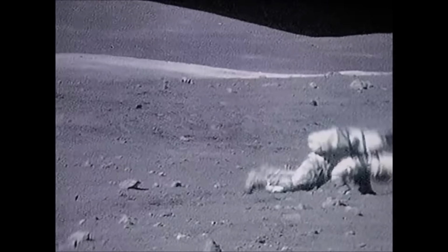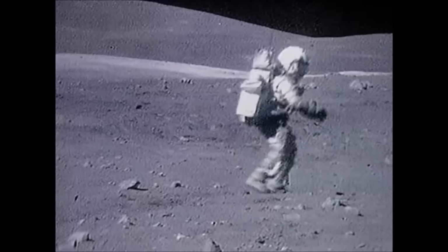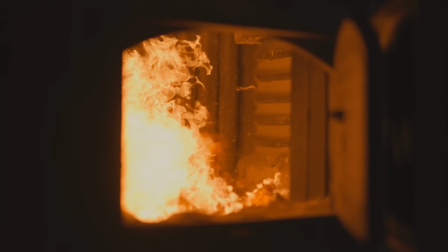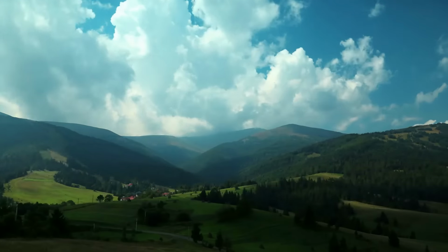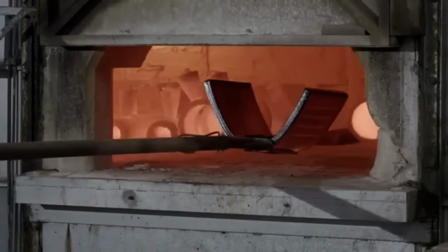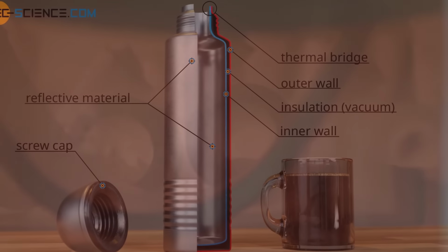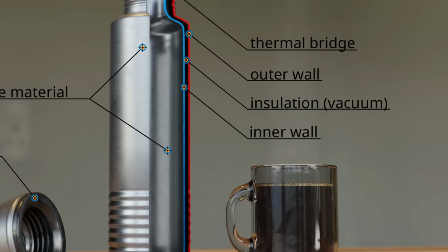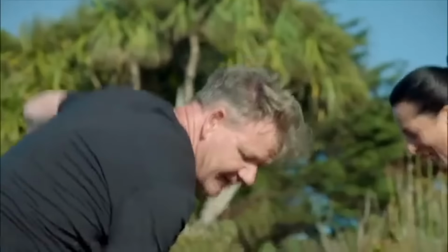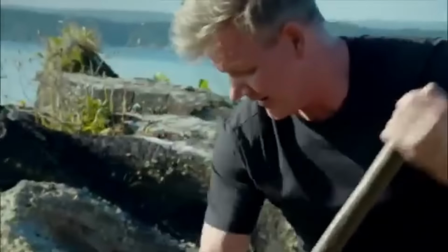The hard lunar vacuum should provide us with a benefit for annealing, as there is no convection to carry the heat away, just conduction and radiation. For annealing, slower is better. On Earth, we have to spend energy to keep things at elevated temperatures, fighting against their natural tendency to cool to ambient temperature, so we do things like put the casts in layer furnaces where we have to spend energy to slow their rate of cooling. On the moon, we can slow cooling significantly by just reducing the heat conducted away using an insulator, and regolith is a great insulator, so for this annealing step we can probably just bury our molds in regolith.